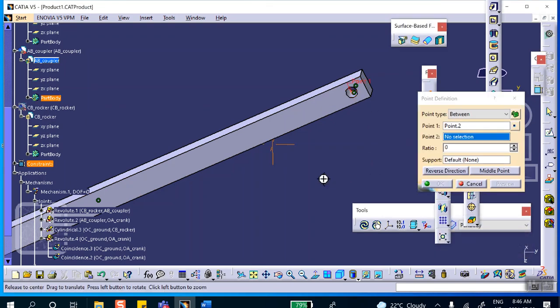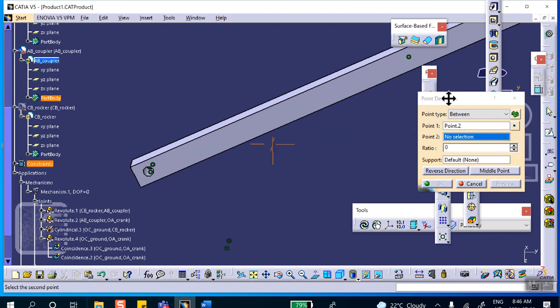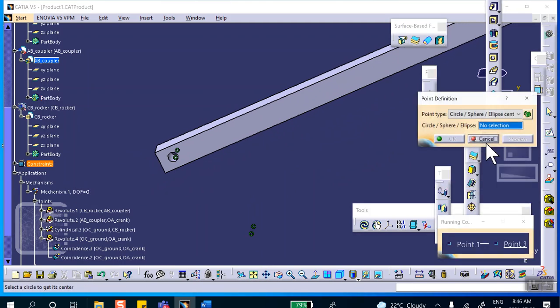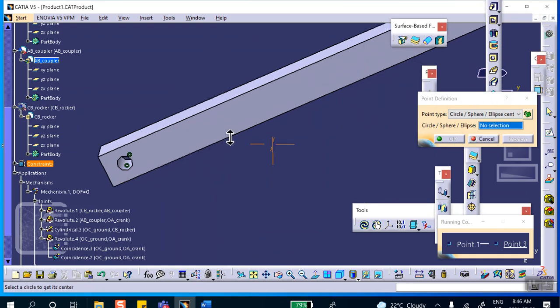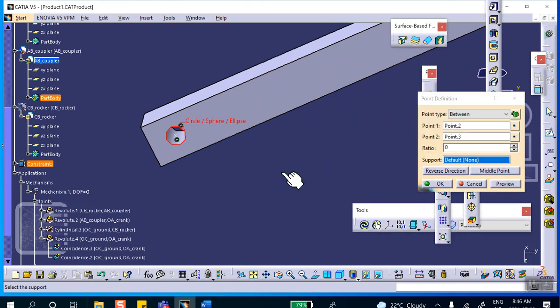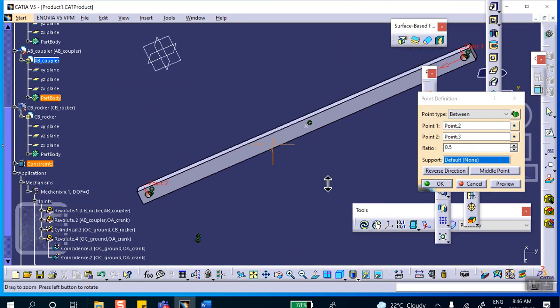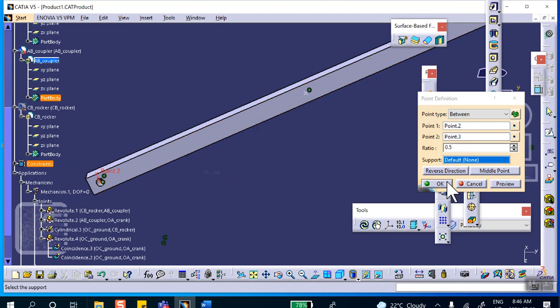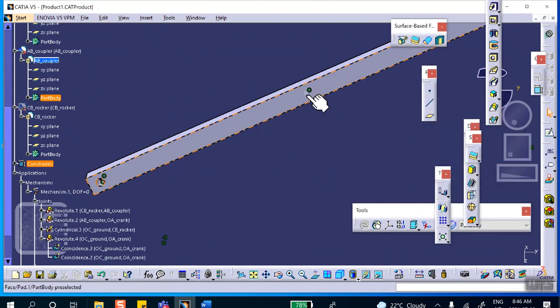Do another one, point 2, right click, create a point, center of that, because I didn't have points there. See, it says create a point between point 2 and point 3 that I just created, and exactly the middle point. So it creates a point exactly at the middle of those 2 points that I temporarily selected. Say, okay, I have a point here, right there.